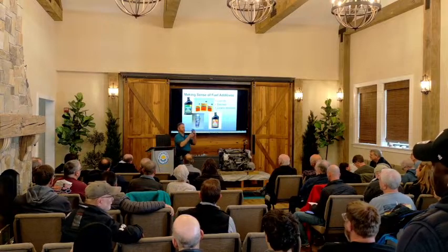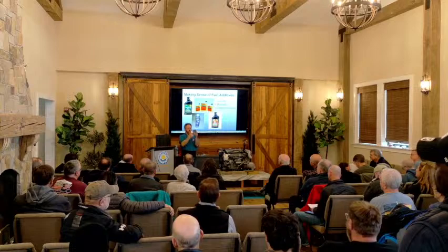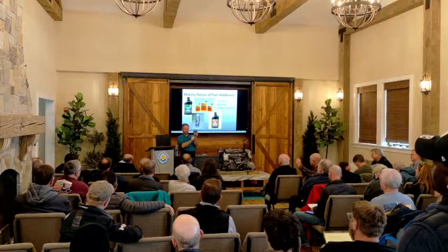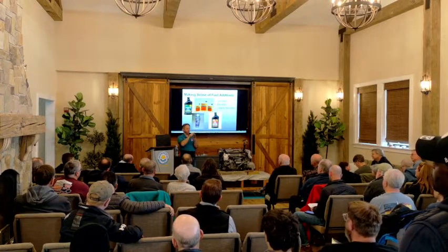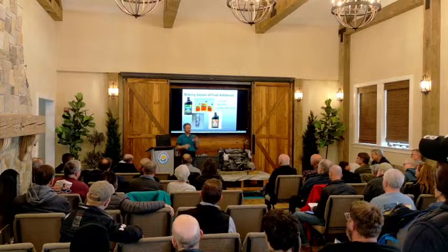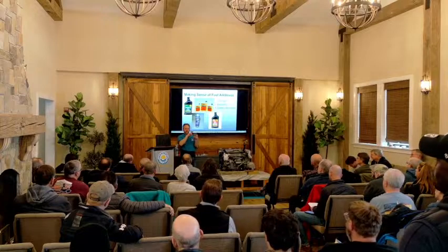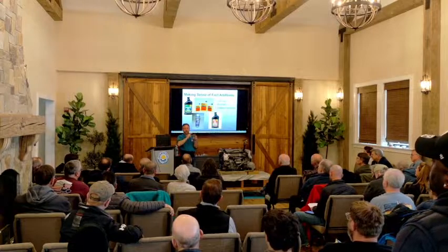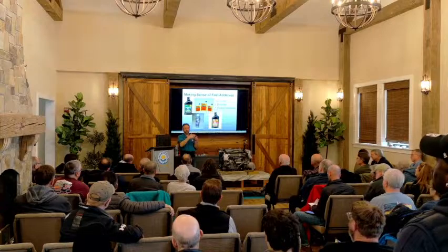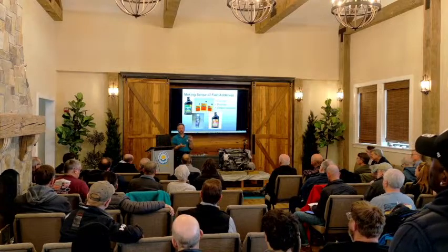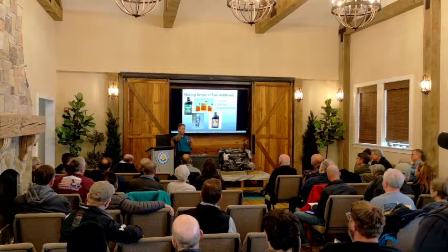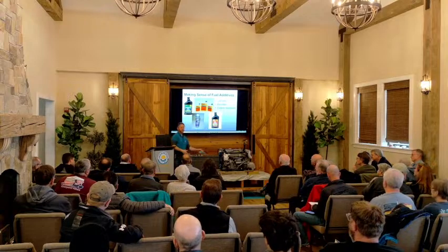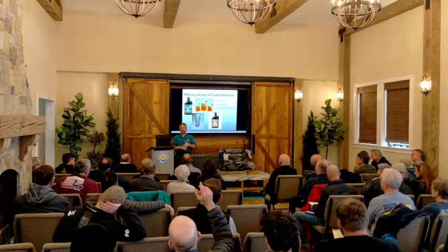So we talked about this injection pump before, the plungers. Once you get a measured amount of fuel into the plunger, the cam pushes up on the plunger, it squeezes the fuel through a tiny little hole and sends it to the injector. If we get air in this plunger, that air is going to compress, and we're not going to deliver any fuel to the injector because the air is just going to be compressing down. If we get enough air in this injection pump, then the engine stalls out and won't restart. Then we'll have to bleed out the high pressure system, not just the low pressure system. So yes, we need to service and get the air out anytime we open up the system.